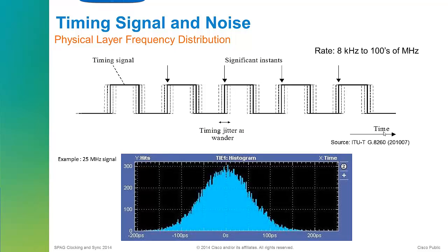So the way a timing signal works is at some point you define these things called significant instants, which I won't really get into, but at some point you define where the signal starts, whether it's a particular voltage or signal strength or so forth. And what can happen, of course, is this can move. This curve can flatten out a little bit. You can get reflections, which mean the signals arrive a little bit early or a little bit late. The signal can get distorted through inductance and so forth.